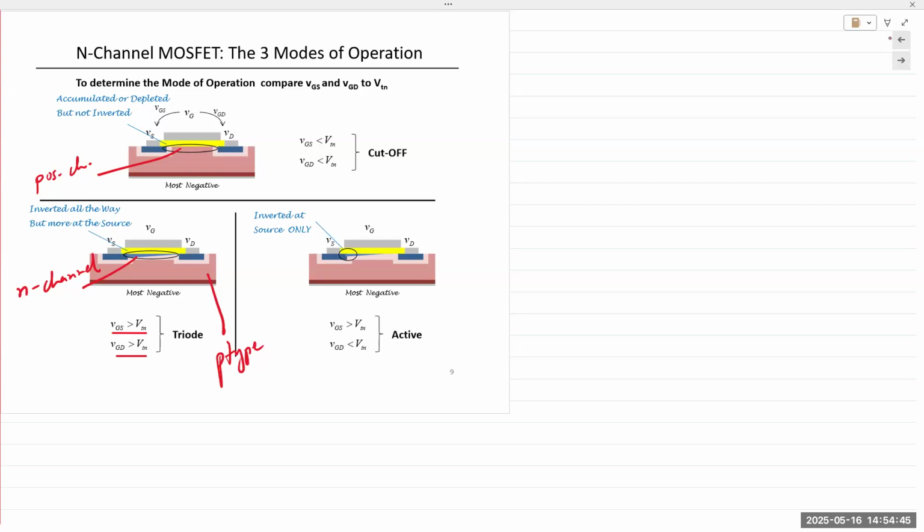What happens when you connect the drain? VDS is positive, meaning the drain is positive with reference to the source. Both are N-type materials. If you apply positive at the drain, electrons are attracted to the drain. So current is flowing in the opposite direction, obviously, but electrons are flowing from the source to the drain via that channel. But at the same time, you're applying a positive potential to an N-type material. So the depletion region starts increasing right here.